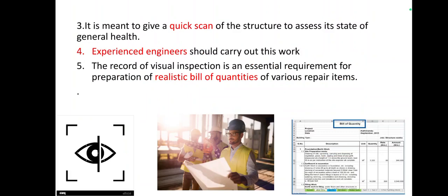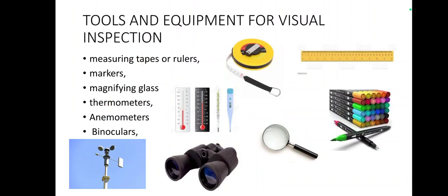Sometimes on the surface we can see a small crack, but it is an indication of spalling due to corrosion also. Once you touch that crack, it can propagate, and it can happen over an entire length, or cover a large area. So if you go and visit, we can come to know the extent of the damage and what the bill for repairing that damaged portion is. We can assess it. And what are the tools we should take when doing the visual inspection?